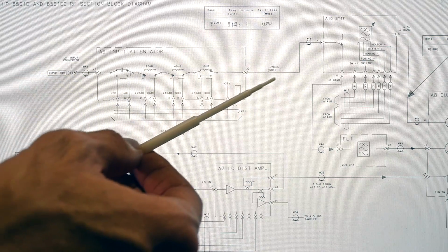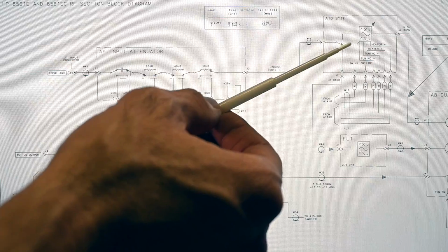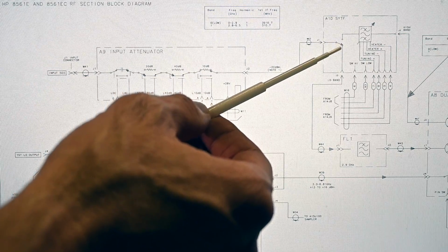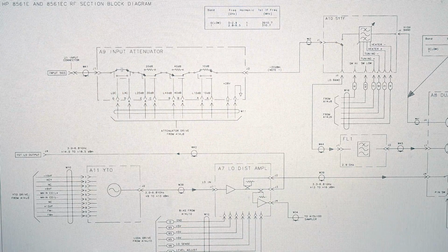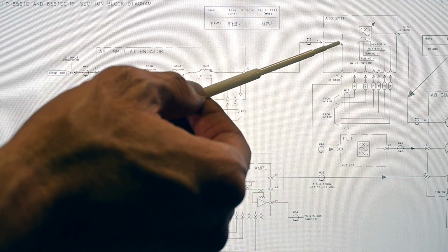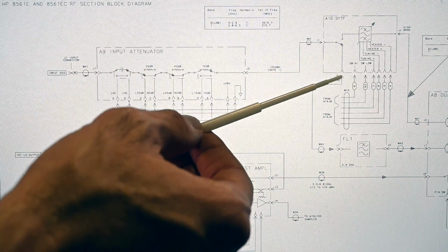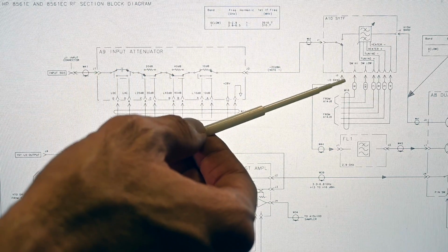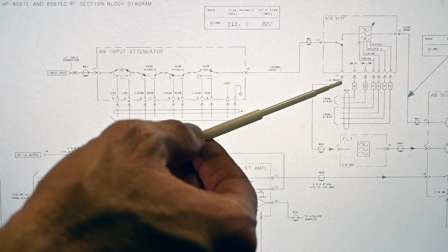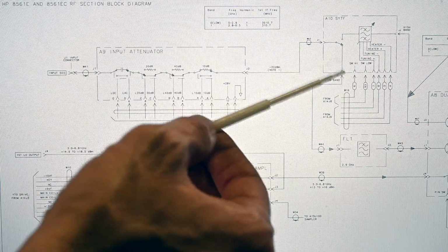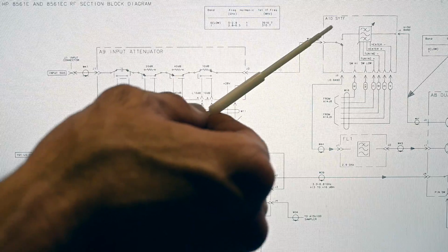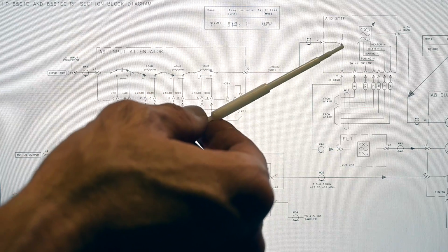And then that signal will come through here. It'll come over to the assembly number 10, but I'll have the spectrum analyzer just sweeping just in the low band so that this is not actually changing position. And then we'll connect the output of this assembly number 10 over to this spectrum analyzer and see what the response is and have an idea if there's a problem going on, particularly with this switch right here.